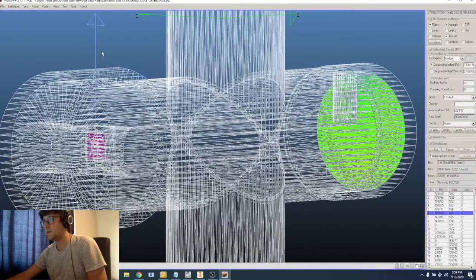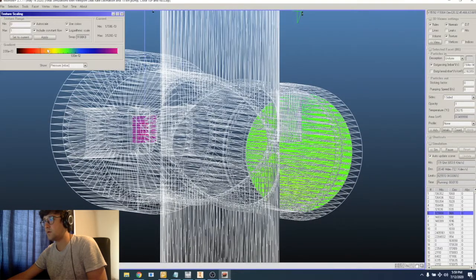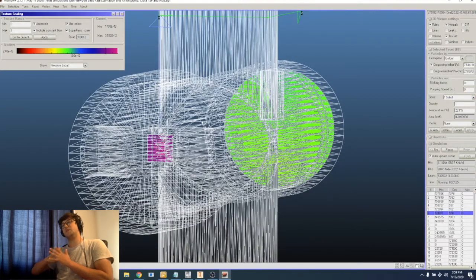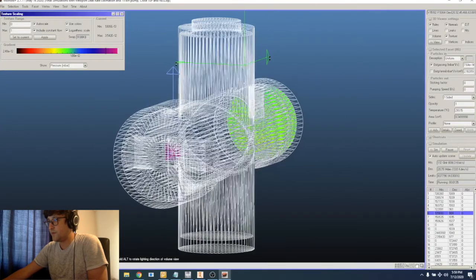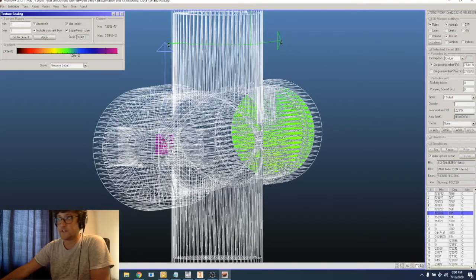If you just look at the texture, we're near 2 to 3 E minus 12 millibar. So about 3. That's pretty good ultra high vacuum pressure. This entire chamber is titanium, so it has relatively low outgassing rates. But this is a decent solution for our specific system.